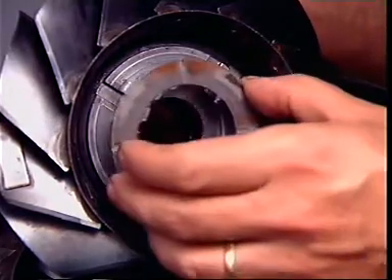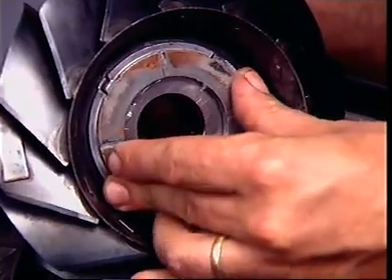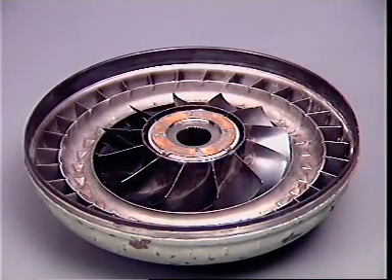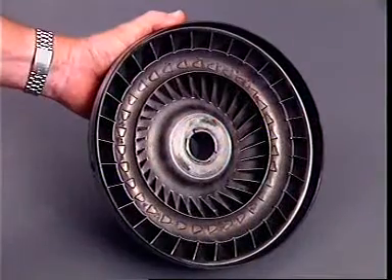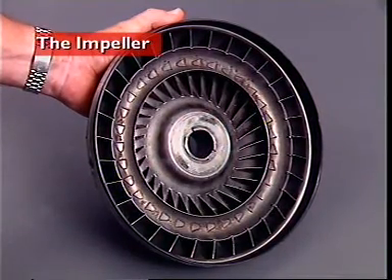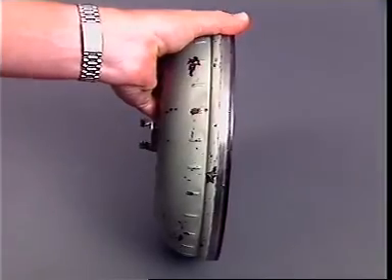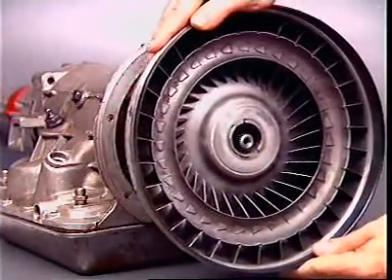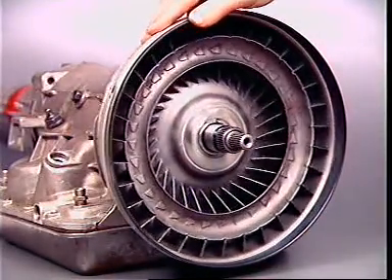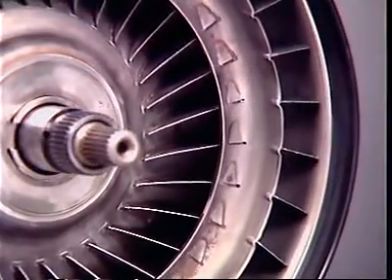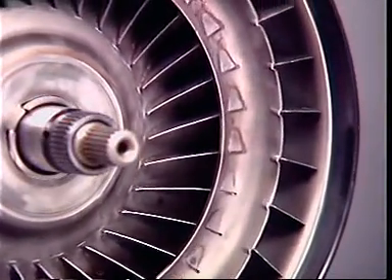They are separated from each other by thrust bearings, but maintain a close relationship for efficient torque transmission. The impeller has a large number of vanes attached to the converter case to form the driving member. The vanes rotate with the casing as the engine rotates. Each one has a slight curvature and is set radially in the case.